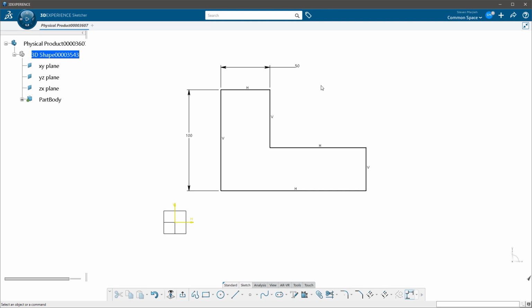Now, other ways you can modify these dimensions: if I wanted to change this and enter in the value, I come over here and pick just once. I don't have to double click on it. By single clicking on it, it takes me into that length parameter. Once again, you'll notice I get driven mode. I can deactivate it, and I go into formulas right from here if I want to. Or if I double clicked on it, it takes me into the menu that drives that dimension.